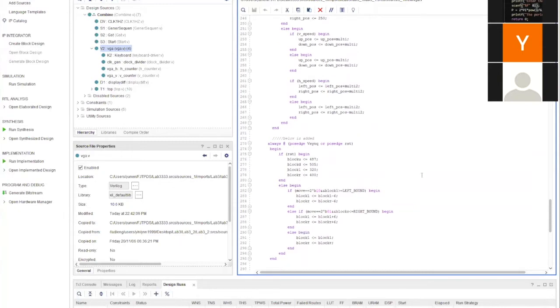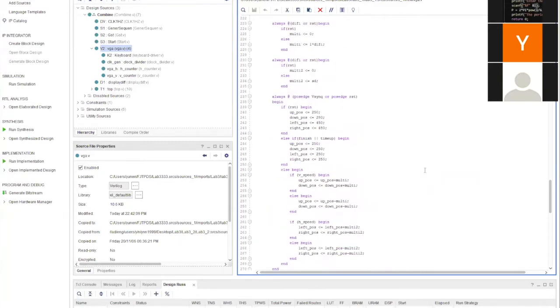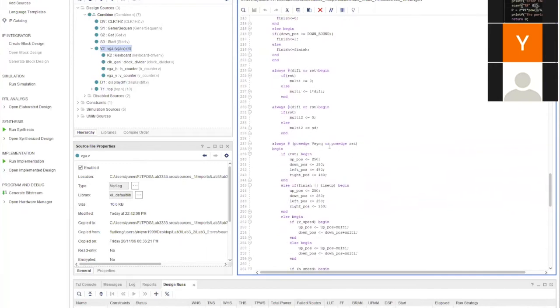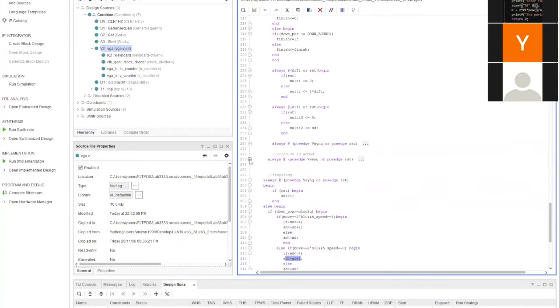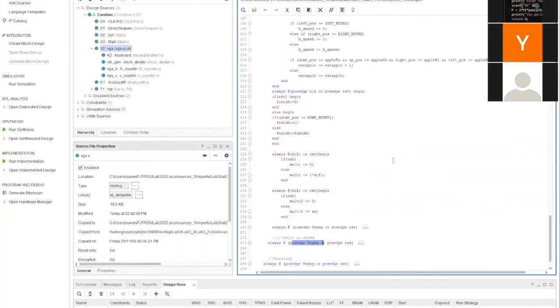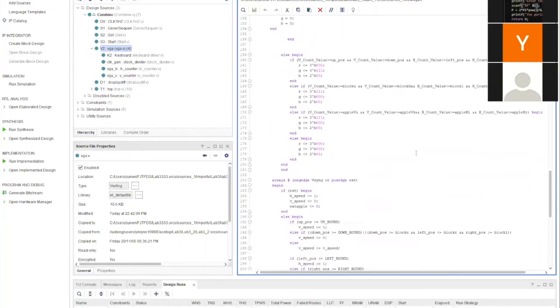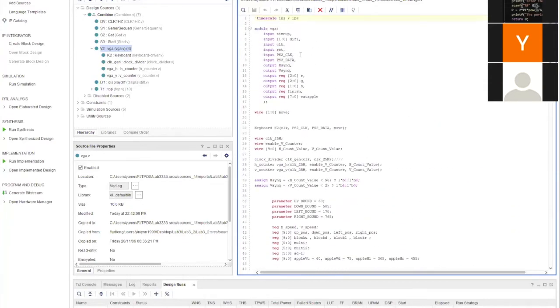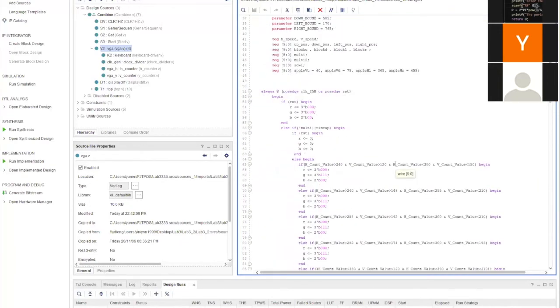So we eventually solved the problem by unifying the trigger, the sensitivity condition of the always block, as you can see here. And we also removed some inputs that had other timing controls. So eventually we solved that problem, and now it is all set.